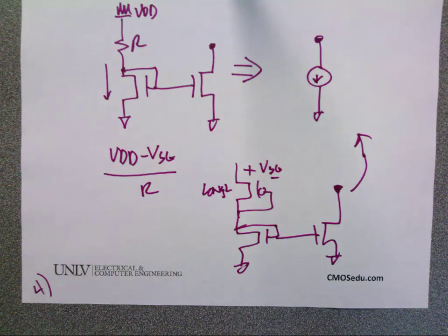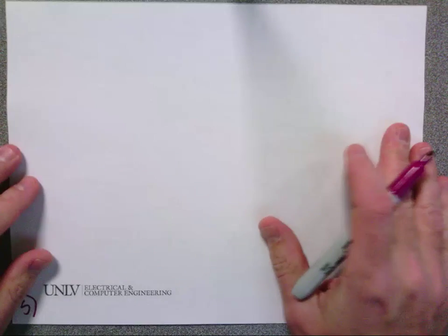This circuit's going to use positive feedback. You might have thought positive feedback is bad, and it can be, but if you use positive feedback with a gain less than 1, so the loop gain is less than 1, you can make a stable circuit. If you have positive feedback like a speaker with a microphone and your gain's greater than 1, you get that screeching sound, right? But if it's less than 1, you'll just get an echo and then it dies out, okay? So consider the following. And we'll do some sims with this as well.